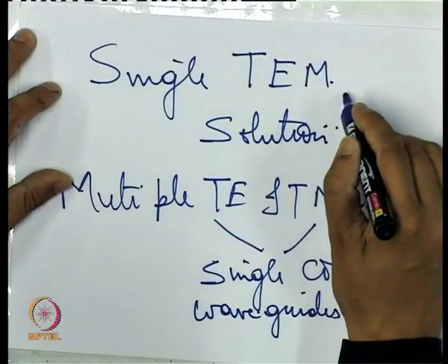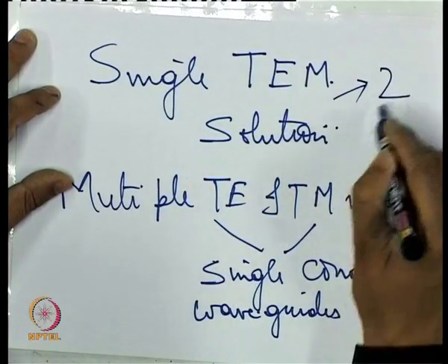Obviously, we cannot have flow of charges as in conventional two wire circuits. So, here these single conductors simply act as a guide for the electromagnetic wave. There is no concept of voltage or current, only the concept of electric and magnetic fields. Whereas, the TEM solution is applicable only for two conductors.